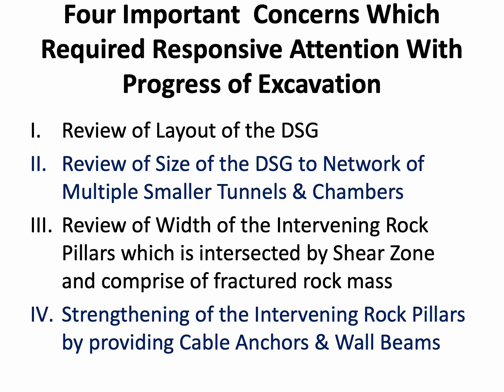Third, review of width of intervening rock pillars, which are intersected by shear zone and comprised of fractured rock mass. Whether the existing sizes were proper or not should have been established.